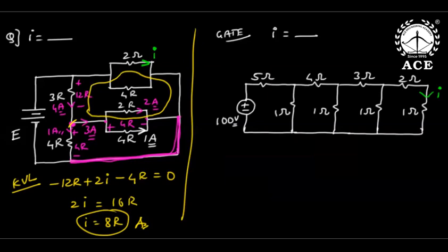Right side is more interesting. Everybody listen to the right side bit. See, right side is a ladder network, sir. Directly, no two elements are in series or parallel. Of course, you can reduce it from the source point of view, but it is a ladder. Now, if you want to find current I, mesh analysis needs 4 equations, nodal analysis so many equations. Instead, I will apply fundamentals like KCL, KVL, and Ohm's law. Actually, I should find I, but I will go ulta.